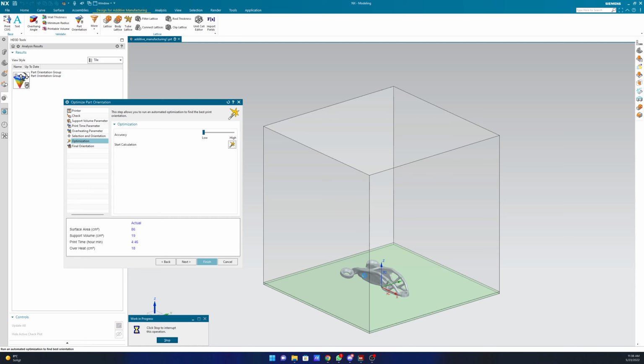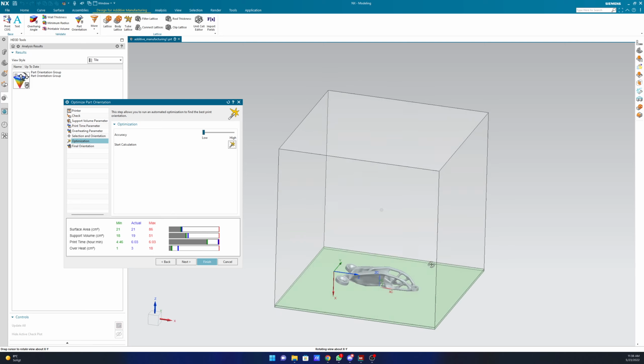But imagine that if you have this part and it's getting stacked vertically in this direction, same part stacked in the vertical direction, the one close to the build plate will be stiffer actually than the top one because the grain size increases as you go up, and that reduces the stiffness. So you will have different properties even if the part is the same. Did you get it? Yeah, I got it.